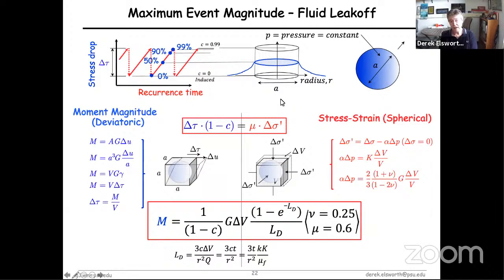I think you get the same happening in hydraulic fracturing. In hydraulic fracturing, the strain energy that you're applying is in the fluid that's compressed within the existing contour of the hydraulic fracture. It's kind of aligned parallel and perpendicular to the minimum principal stress. And so it would not so much rupture in shear, but you could rupture it, I guess, beyond the rupture, as you do in a hydraulic fracture, just due to the strain energy.